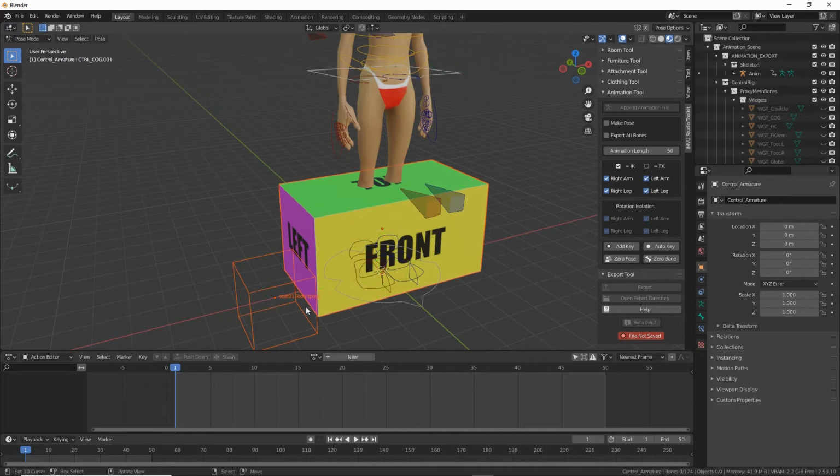What we need to do is move our furniture object, or the mesh and the root node. And we need to position the origin of the root node, that's that little dot that we can see, at the origin of the avatar, which is highlighted in this particular instance by the 3D cursor. We need to do this manually, and it doesn't need to be exact, but it does need to be roughly approximate. And to do that, we just need to quickly drop into object mode.